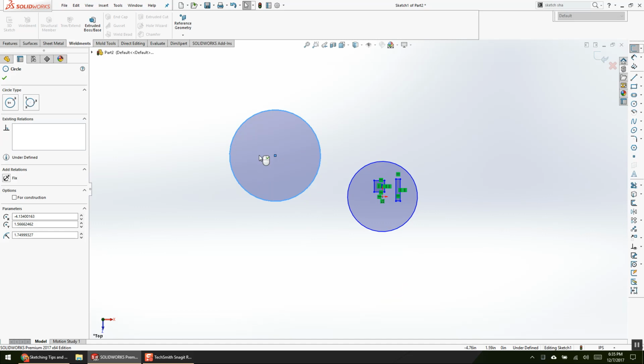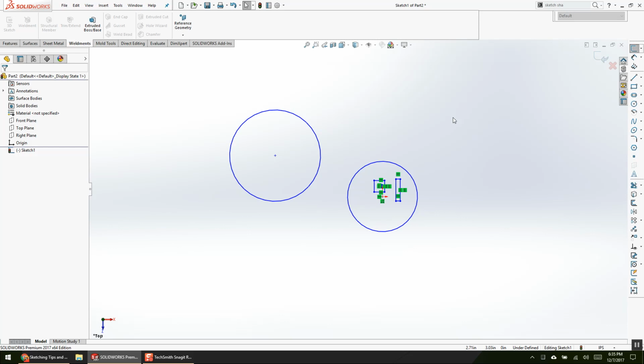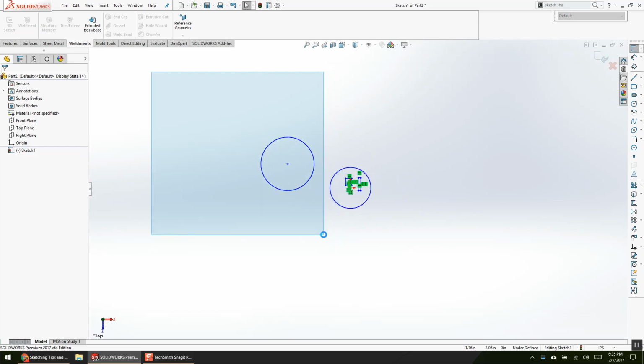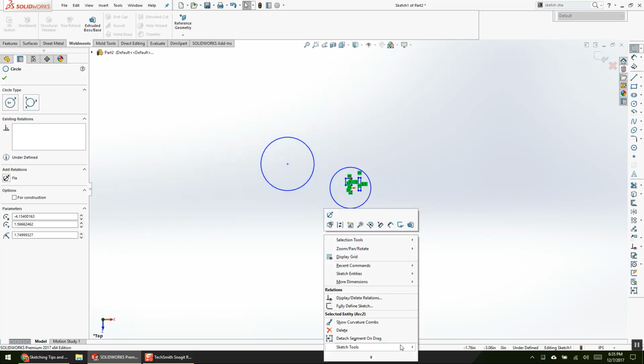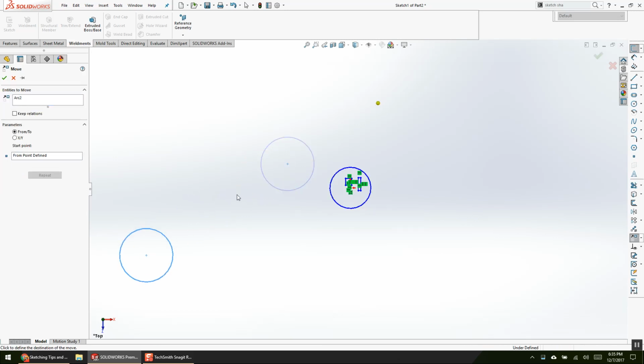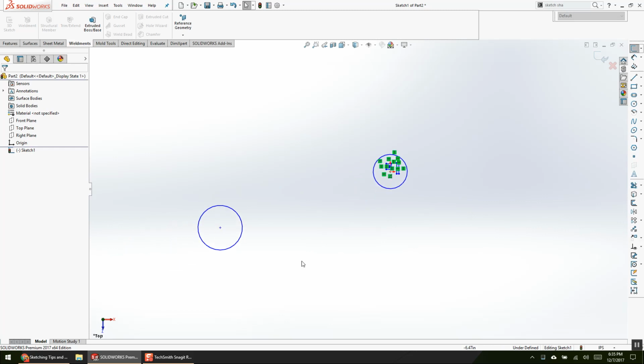Like, in a normal day's worth of work? Never. I think I do it 3 times a year. So there's a setting called sketch or shaded sketch contours, and you turn that off and it reverts to the old versions of SolidWorks. If you do want to move something, you can still select it, right click under sketch tools, move entities, and you can still move things around. So you could always move things in SolidWorks. They just made it easier to do something that we virtually never ever do.